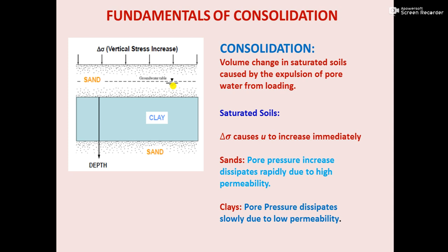However, on the other hand, the clay is not that highly permeable. The low permeability of clay will not allow the pore water to dissipate very fast, right? It will not allow the water to leave the soil mass very fast.